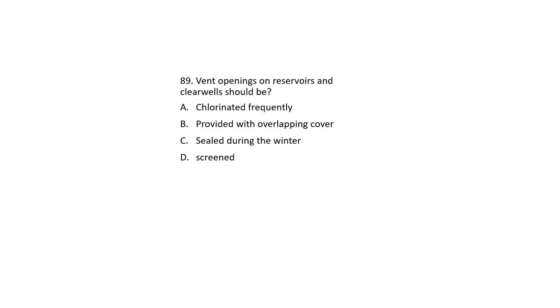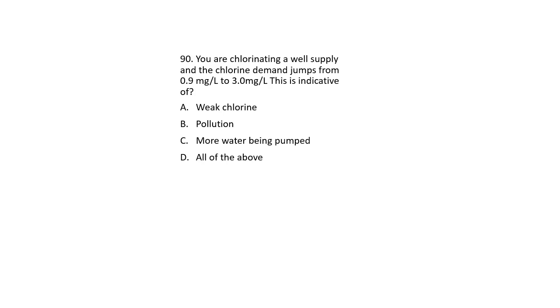Vent openings on reservoirs and clear wells should be chlorinated frequently, provided with overlapping cover, sealed during the winter, or screened. Answer is screened. You don't want animals getting into your clear wells or reservoirs and dying.